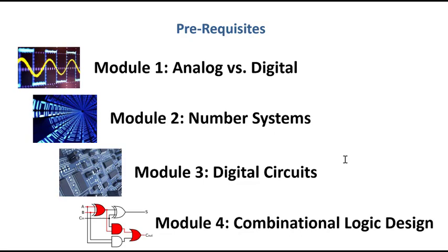And we also needed to look at the interfacing between gates. So if one gate is going to produce a logic 1 and it's represented as a certain voltage level, the gate that receives that information has to be able to interpret that voltage level as the logic 1. So we needed to be able to design circuits that can interface with each other, and we needed to be able to understand the operation of these gates in order to interface them properly.